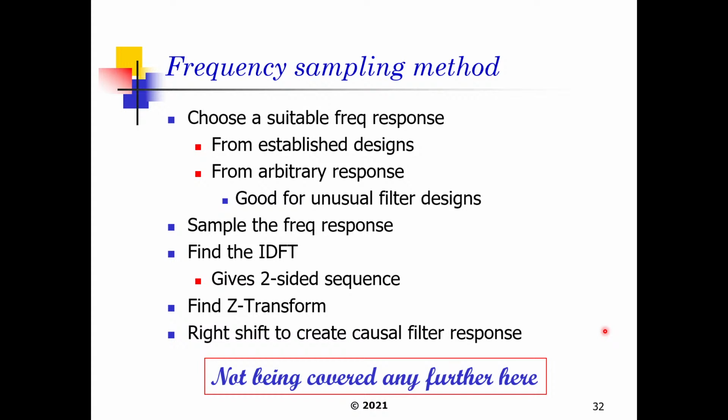And then we calculated our vector for our window function, and we just multiplied the two accordingly to get our filter vector. And then we just transfer that into our z equation, and then we move from the anti-causal form to the causal form by delaying the samples accordingly.